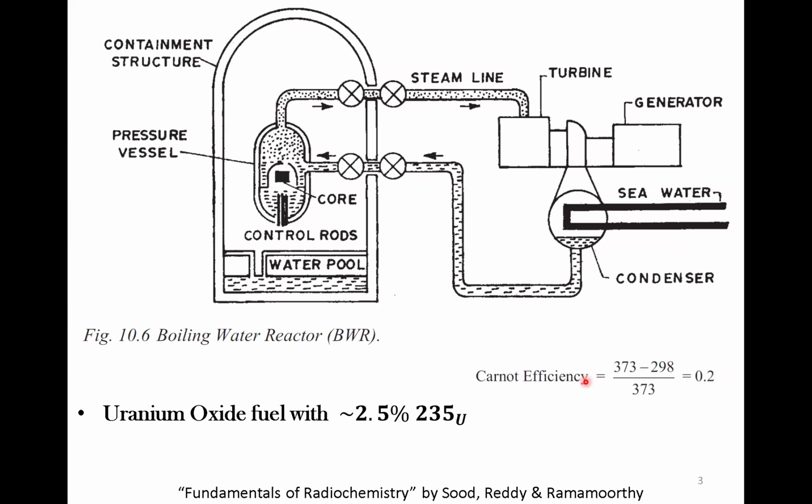The Carnot efficiency depends upon the high temperature reservoir and the low temperature reservoir. So supposing the low temperature reservoir is 298 K, why do you say this? Because the low temperature reservoir is usually a heat sink that is available to you, that is usually a water body or the atmosphere. That is at this temperature. So the essential control is on the high temperature reservoir.